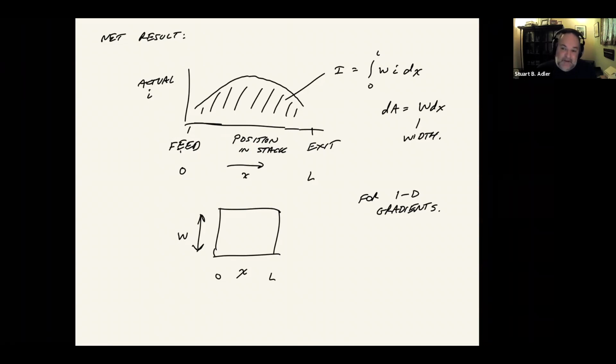Generally speaking, the same things hold. Where you have higher temperatures, you tend to have higher current density. Where fuel is the freshest, you tend to have the higher current density, as you might expect. If we really want to know what's going on in the stack and really make a meaningful calculation of cell area, we need to model these gradients.